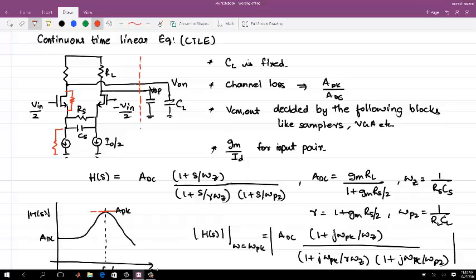So whatever RS value you calculate in a scripted form or a MATLAB simulation or something, you need to take the gds into account when you later put the RS value in a real circuit. And similar things will happen for the capacitance. The extra parasitic capacitance will exist here due to both the top and the bottom transistor. So you need to accommodate that within the CS value.